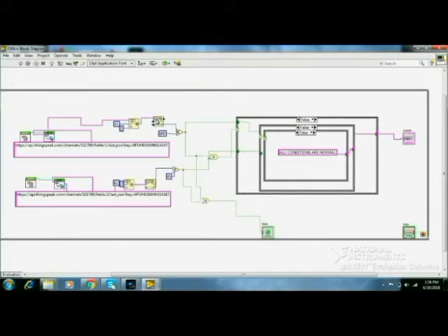This field was to store the RPM of the indoor fan. Now we check whether the RPM is less than the set value. Here we check if the RPM is less than 800. If yes, the case structure for that is selected and an alert message is printed. The same steps are followed to monitor the motor complaint. The only difference is that we use the reading from the temperature sensor, that is, the stored value in field 2 of our channel fan issues in ThingSpeak.